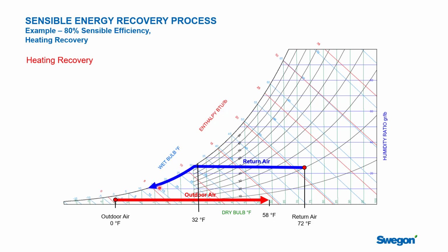But ultimately that frost will block off the device. And so this is not a stable operating condition. It can happen short term, but is not something that can go along. There's a very clear example of what it means to frost an energy or heat recovery device.